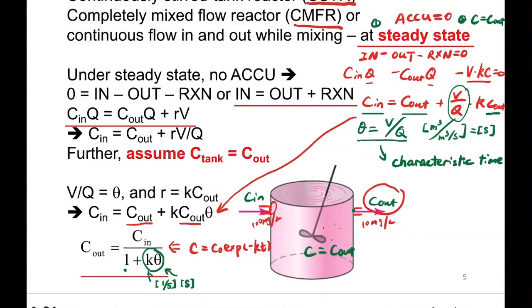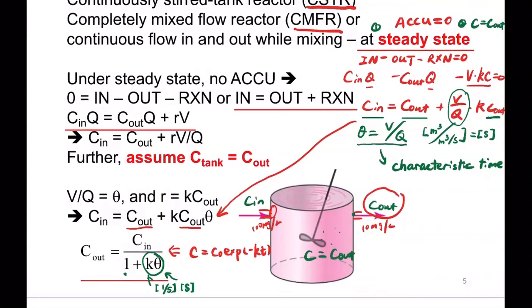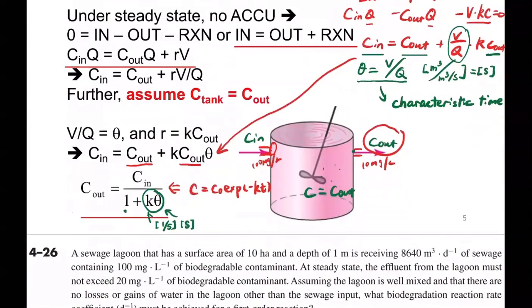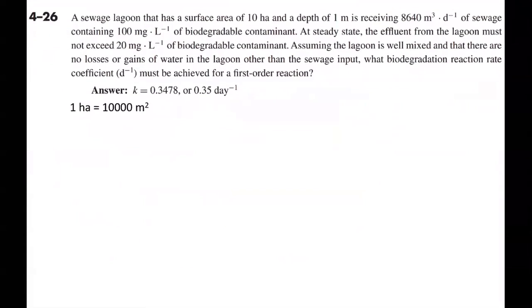So we want to mention that basically we changed from a batch reactor to the CSTR, but we also completely changed the concentration at the outlet of the reactor, right? One is an exponential term and one is just a linear term. So now we can do another practice for this CSTR here, right? I'm showing this problem here. We can spend maybe another minute to look at this problem, to just practice this calculation here.